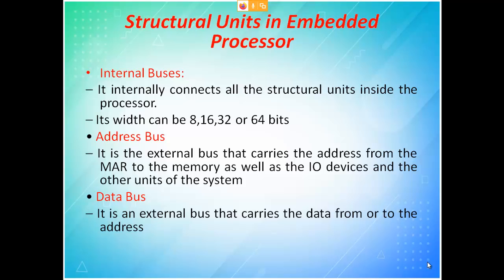That is done because whenever you declare an address, initially from the processor I will send the lower order address, then I will send the higher order address. When I am sending the higher order address, at that point of time the lower address lines are free, so I can use them for data. That is why sharing is possible. A well-known 2-mark question they will ask: what is ALE, which is address latch enable. With that we are able to do that.